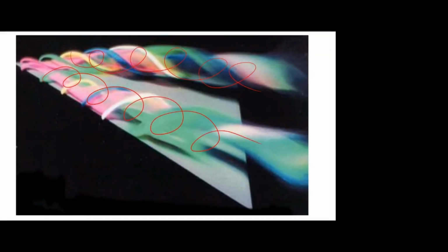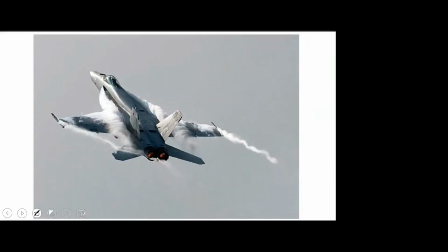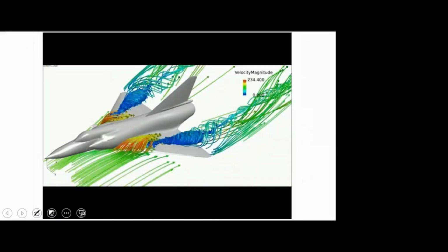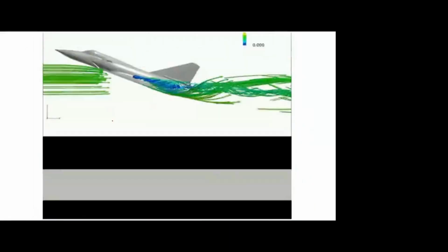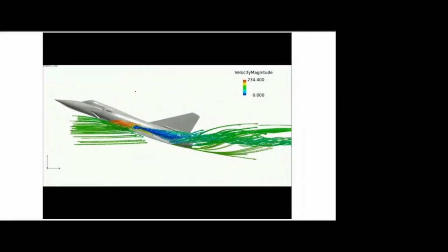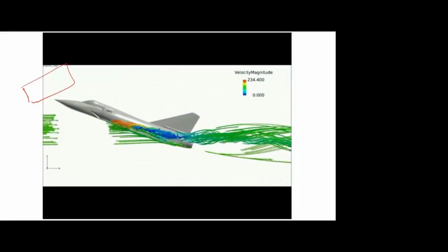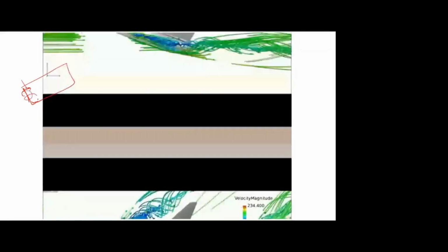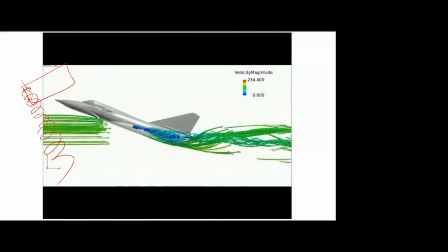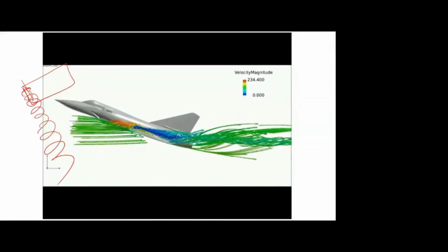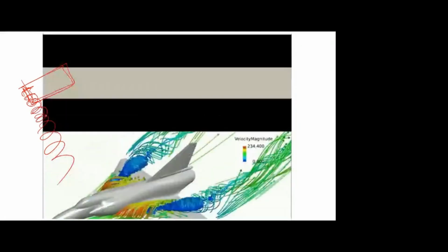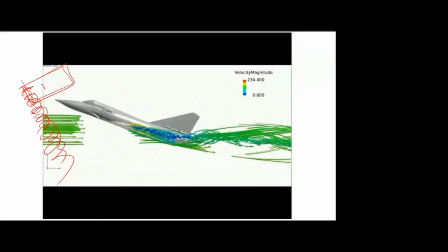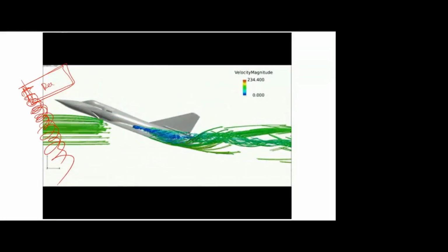So there will be vortices on the wing because of this shape. Here also you can see, this is the simulation. The same concept as the normal wing we studied, right? Due to the pressure difference, there will be a side leakage flow. It will be pushed rearward, so it will form wing tip vortices. But the difference is, if we take a rectangular wing, on that wing there will be only the side leakage flow, and the vortices are formed only behind the wing.